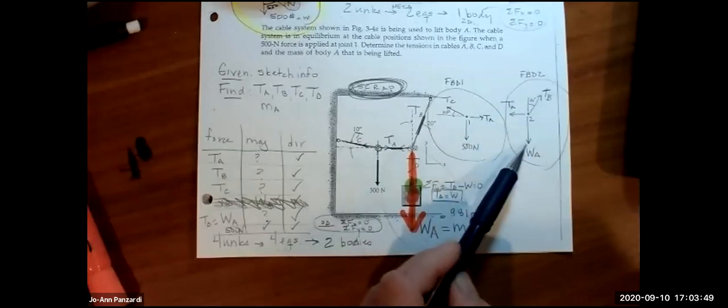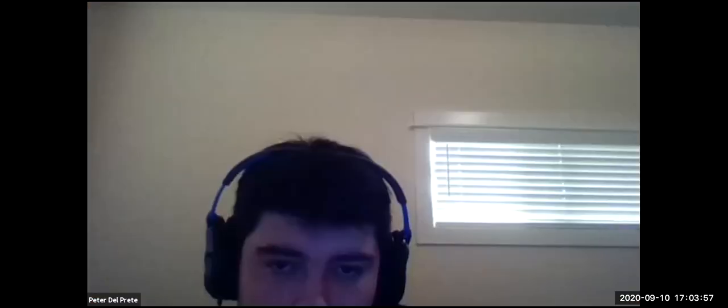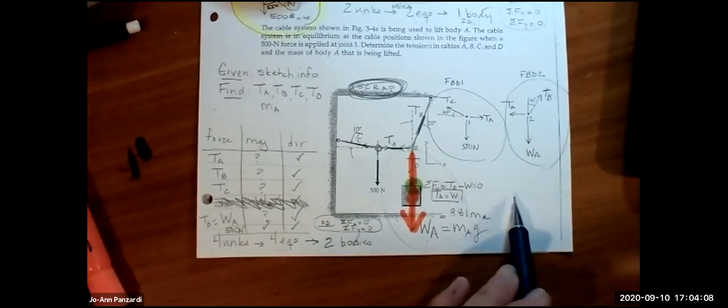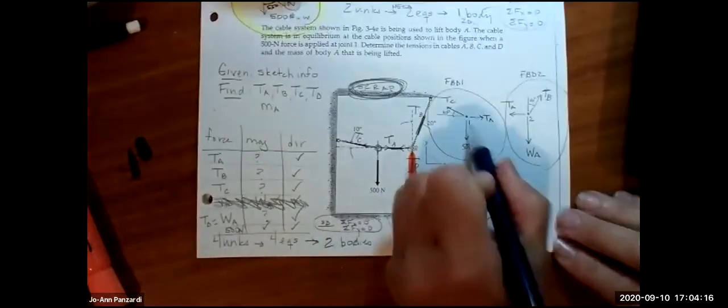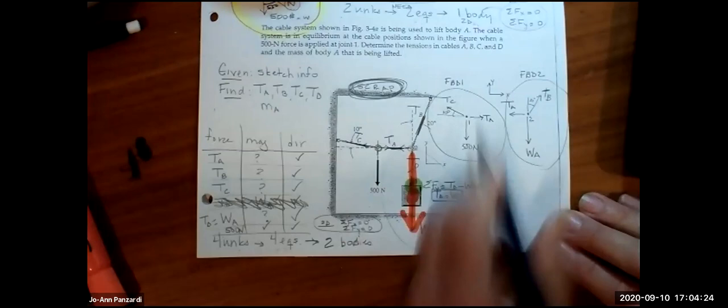But I have something missing, a critical thing that's missing from the free body diagrams. I have all the forces labeled with the directions, but I have something missing. What is it? Would you want to break up tension TB and tension TC into X and Y components? I could break it up, but I'm not going to because I could just do the math later on. What about axes? Oh right, yeah, you need to draw the axes. Okay. So you could draw the axes on each one if you want. If you want, you could just draw it off the side. But you have to have an axis in there.